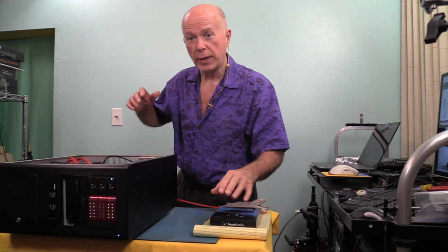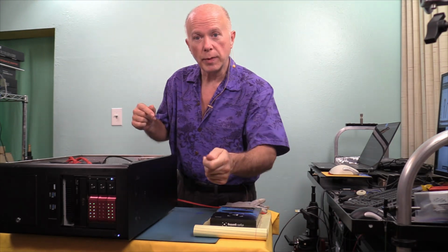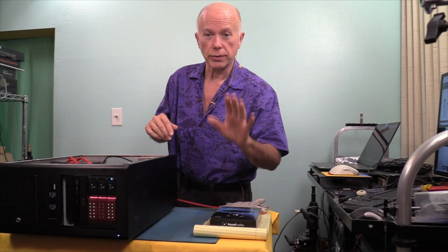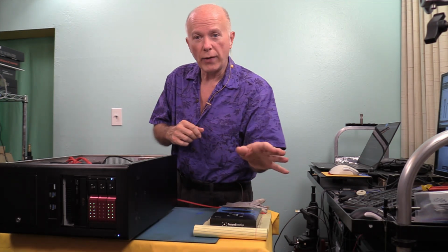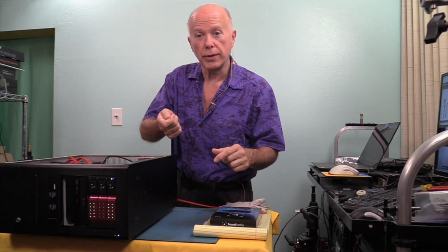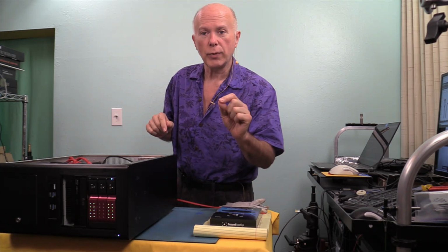We've looked at some of the ultra thin or ultra slim cables like Monoprice. Those are Redmere. Do not get involved with Redmere cables. What will happen? They will appear to work sometimes and they won't work other times. You can unplug them, plug them back in, and they'll work. And then the next time you plug them in, they won't work. Believe me, I did a whole lot of that, and that's a real hassle. Nothing wrong with the cables, it's just the technology is not quite where it needs to be. So stay away from Redmere cables. They've got smarts in one end that allows them to boost the signal, and it's not worth the trouble. Stick with something simple, but stick with those ultra thin cables.